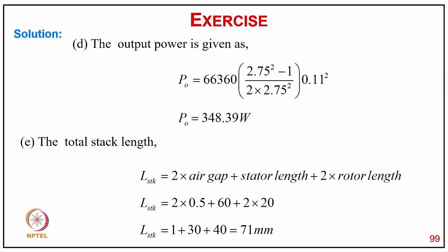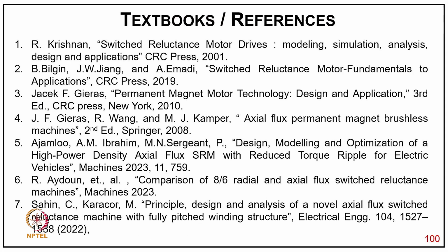And the total stack length is Lstk equal to 2 times the air gap plus the stator length plus 2 times the rotor length. Putting in the values here, Lstk comes to 71 mm.